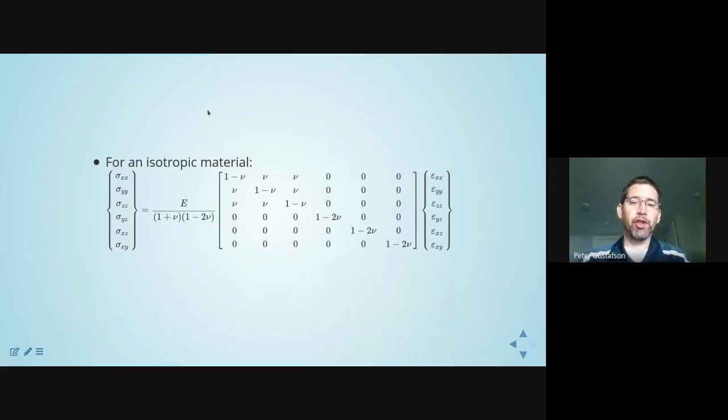And what we have is a relationship between stress and strain, now written in a matrix representation of the tensor relationship. So you have to remember this is a tensor relationship. On the left-hand side, we have 6 stress components shown here. On the right-hand side, we have 6 strain components. Keep in mind, of course, that we're showing only the unique stress components, but the tensor actually has 9 components in it, 3 of which are not unique. Same with the strain components.